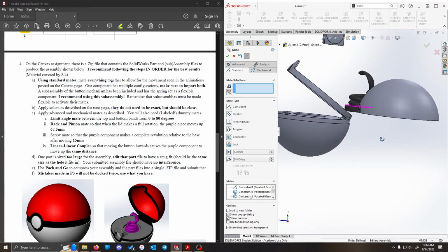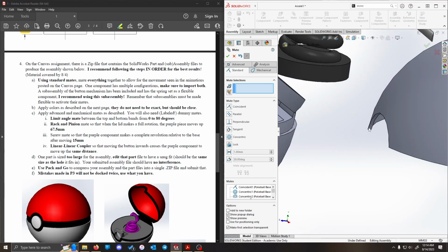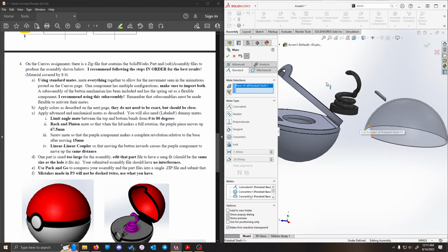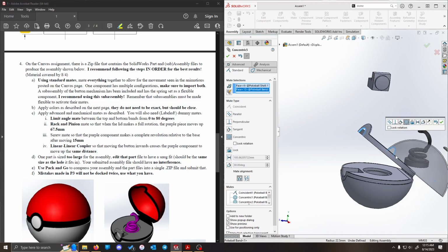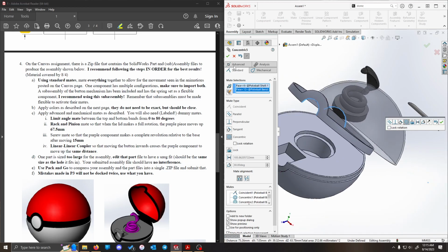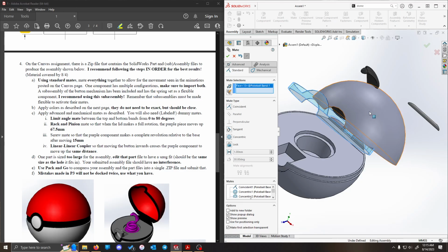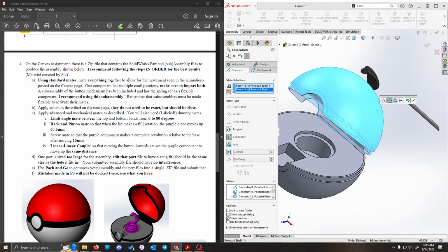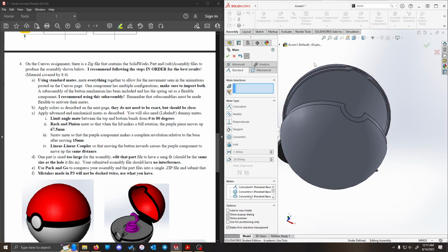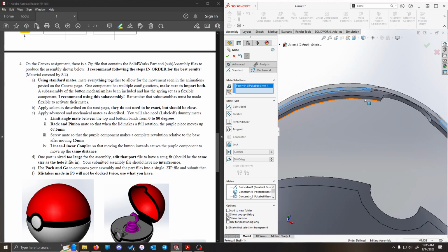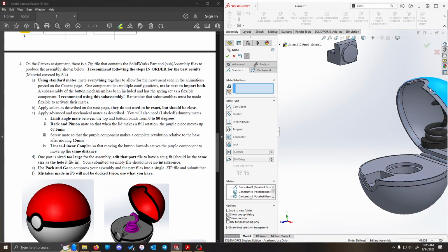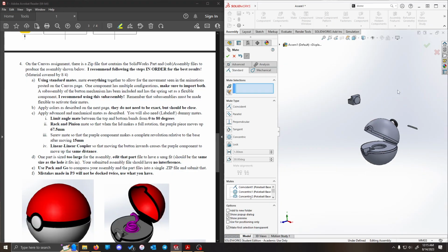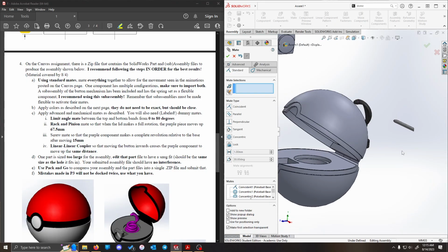All right, next up, the other sphere. So I'm going to just do the cylinders first. So we got that one and that one. We're going to need to be concentric. Then we know that the spheres are going to be concentric. And then we know that the flat edges are going to need to be parallel. Cool. So testing it out, the hinge works. Still need to put the pin in it though.